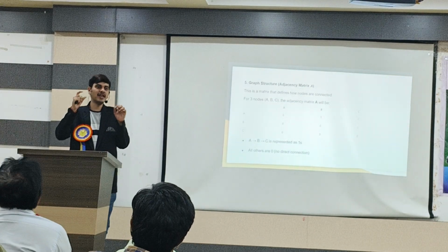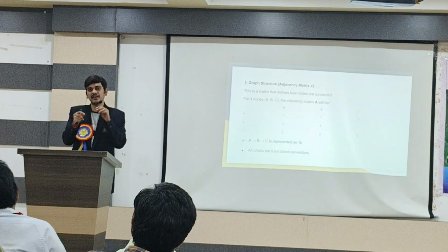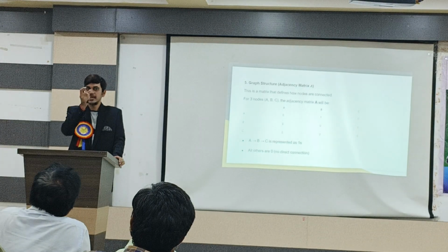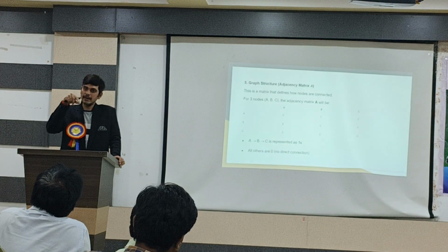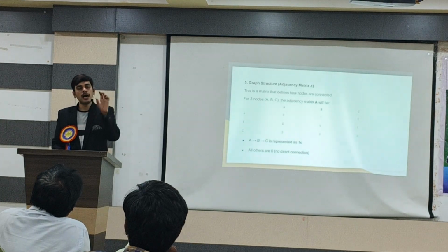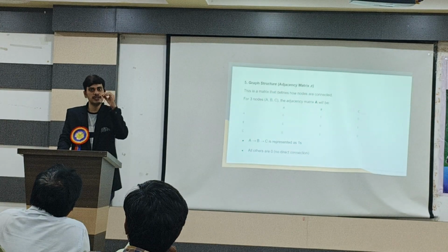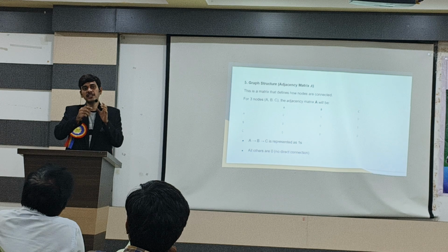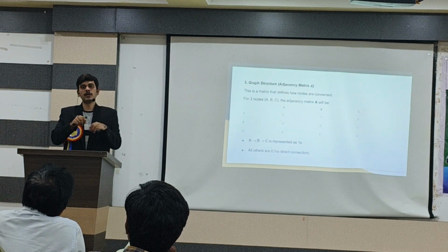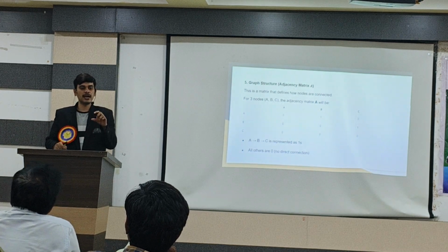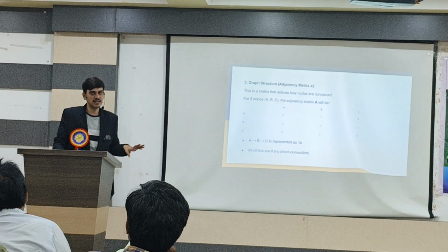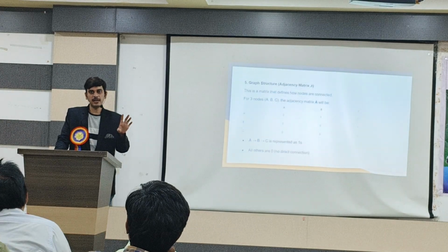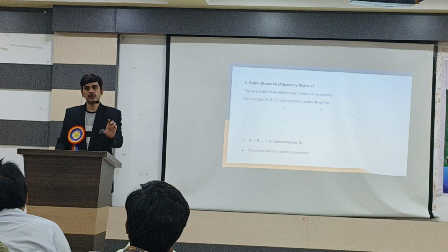So we have to check that different cells are there. There is a variation between setup and hold. A cell will have a 10% variation in setup and hold, and the delay cells have 20% variation. So based on the variation, which cell we introduce in the timing fix, the timing board will decide. Based on that, we have to decide which cells to use.